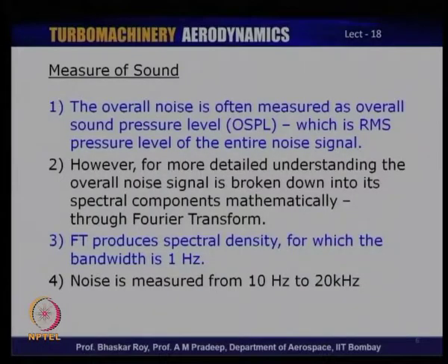The measurement of sound then becomes a little more complex issue. The overall noise is often measured as overall sound pressure level, or simply OSPL, which is the RMS pressure level of the entire noise signal composed of all kinds of frequencies and amplitudes. So, this is kind of an overall average noise and is often simply measured in terms of dB as the overall noise.